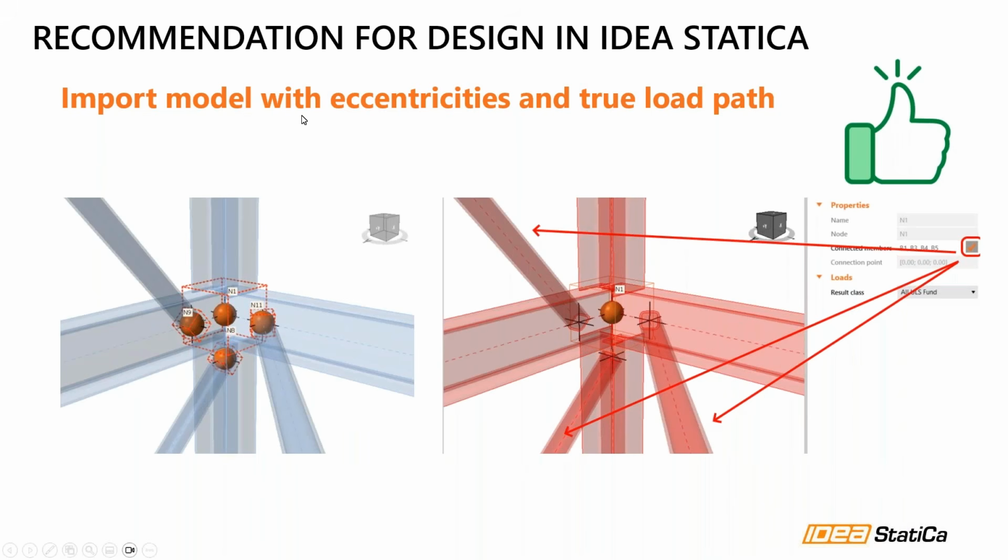So our recommendation is to use the model with the eccentricities, export it to IDEA StatiCa Checkbot, and do the design inside IDEA StatiCa Connection.